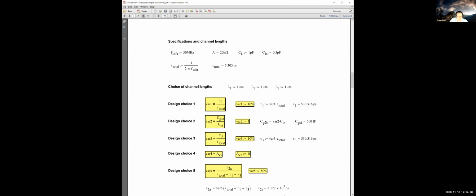And that's where designing this circuit and going through all of the hand calculations, it's really important to understand if the bandwidth comes up short, how do I increase it? If I have extra bandwidth, how do I reduce the bandwidth and save power? You need to know what these trade-offs are. There's too many knobs in the circuit that if you just go wildly trying to tune every one of them, you'll never figure it out.